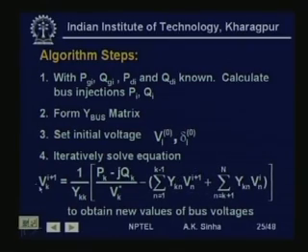That is, if we are doing it for bus 5, then up to bus 4 we have the updated value for I plus 1th iteration. So, we are going to use that. So, this is what speeds up the solution somewhat. So, this is how we work for the Gauss-Seidel method to obtain the value of the voltages.